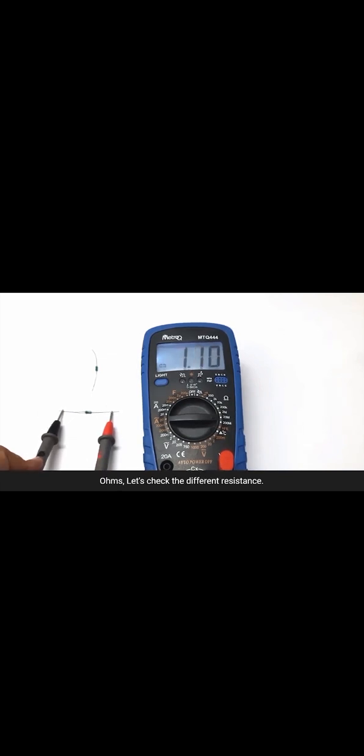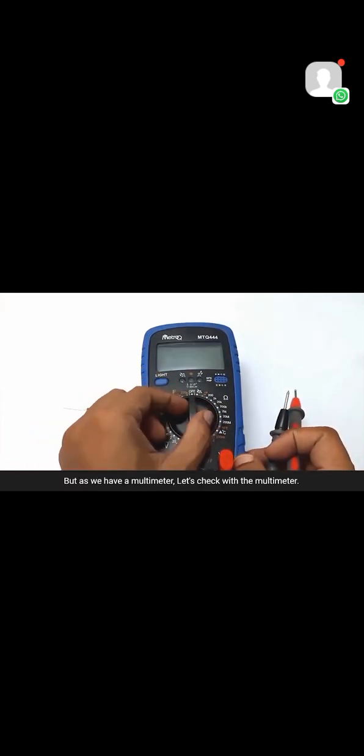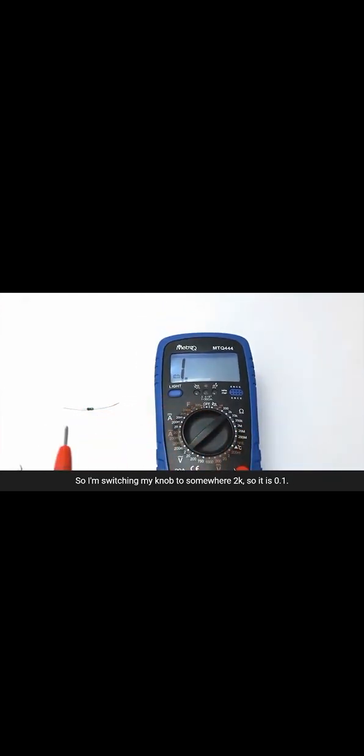Let's check the different resistance. We have this resistance here. We can also calculate the resistance value with the resistor calculator, but as we have a multimeter, let's check with the multimeter. So I'm switching my knob to somewhere at 2K. So it is 0.1. Let's reduce the value.